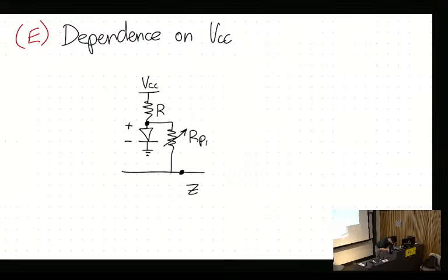So what we can see here is that the power supply powers that diode, but it clamps the voltage down to 0.7 volts, and that voltage is what's being used as our reference to trim. So it has almost nothing to do with VCC anymore. VCC is just for the diode.